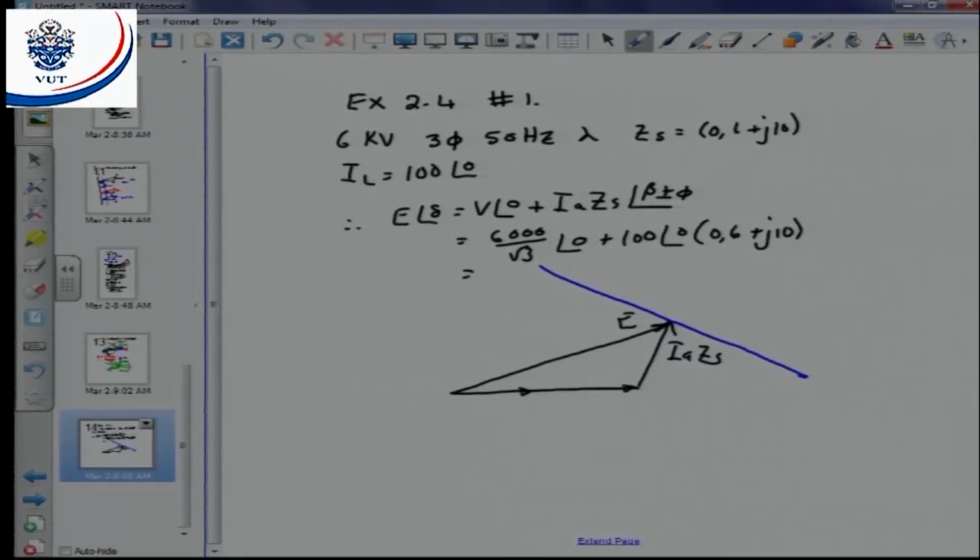Now, with the aid of a load diagram, determine the armature current and power factor at which the machine will operate if the power input is increased by 100% while the excitation remains constant. Now that means that our power will have doubled and the new power line will lie there. With E constant, it will rotate until it reaches that point on the graph there. So that is our new load angle.